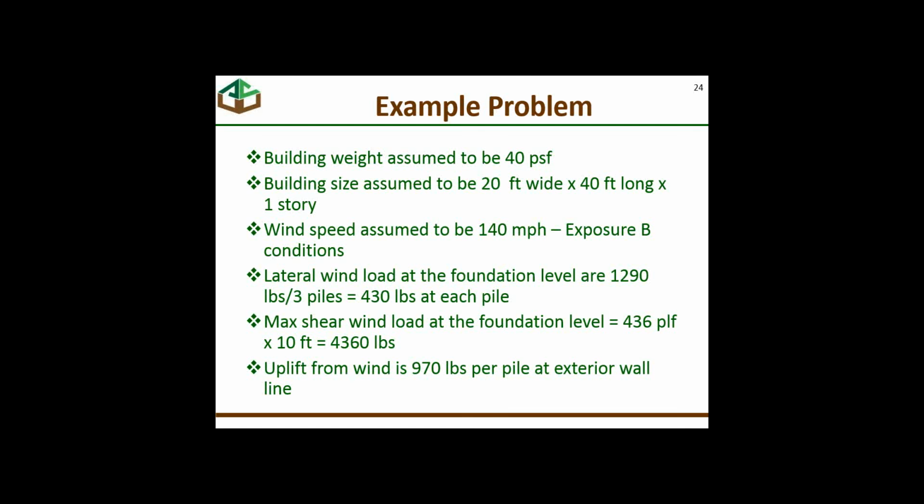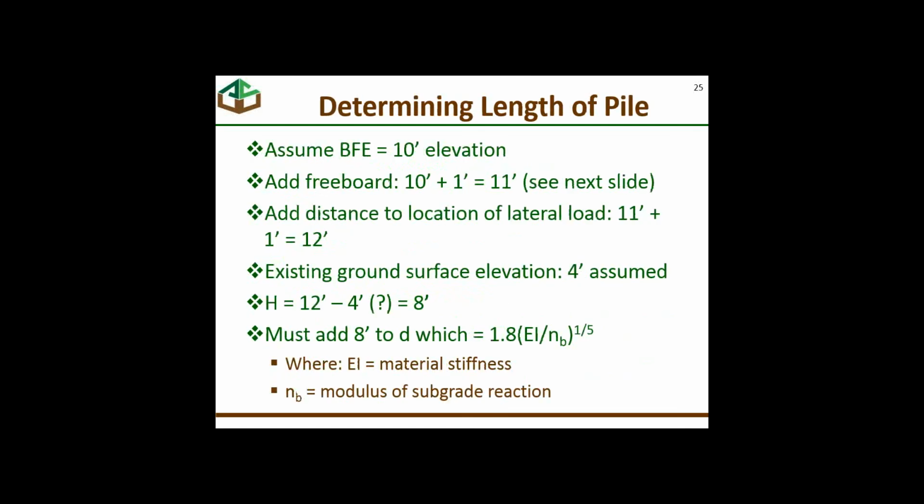The only thing that could be different might be, at least in this case, that for shear walls, we're likely to brace those shear walls potentially and maybe not need braces anywhere else, or maybe only need braces in the corners perpendicular to those short walls, and then we wouldn't need braces anywhere else. That would be one of those places where we could make a change, and contractors would find that perfectly normal and would know how to deal with it.